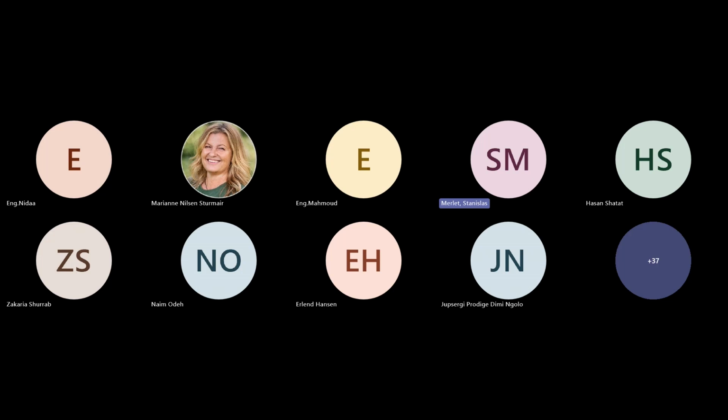So first, it's very much linked to the diffuse irradiation, as Michel mentioned on Monday. It's also very much linked to the reflected irradiation. So whatever light comes onto the ground and is reflected by the ground to the back side of your module. And this is related to albedo. I don't remember if Michel covered it, but that's the ratio of light that is reflected against the light that is absorbed.